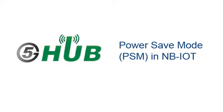Typically, IoT devices tend to send or receive data at irregular periods, and between periods of data transmission and reception, the device can be put to sleep to optimize battery consumption. So in this video, we will talk about one of the features used to minimize power consumption, called power save mode, or PSM.